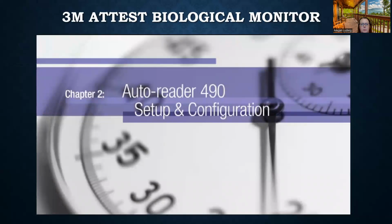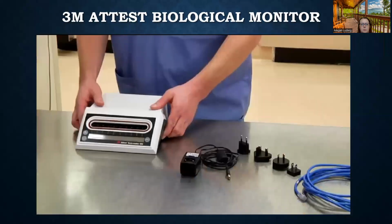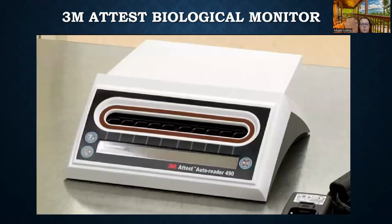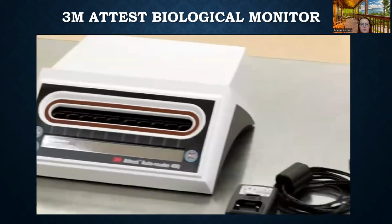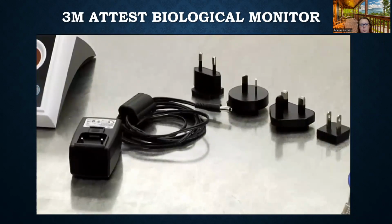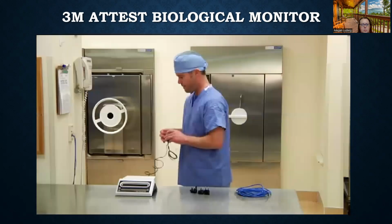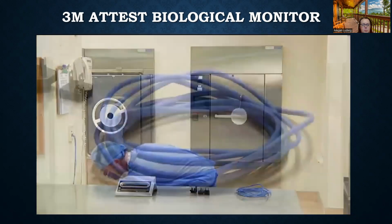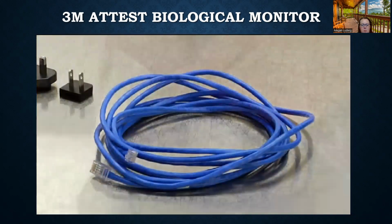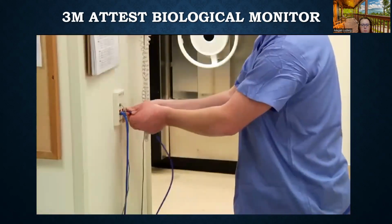Setting up and configuring your 3M A-Test Auto Reader 490 is simple. First, place it on a firm, level surface near an outlet, away from sunlight and incandescent light. The A-Test Auto Reader 490 comes with multiple power plugs for use in different countries. Select the plug appropriate for your country and insert it into an AC grounded outlet. If you plan to use the A-Test web app, connect the supplied Ethernet cable to an Ethernet jack.